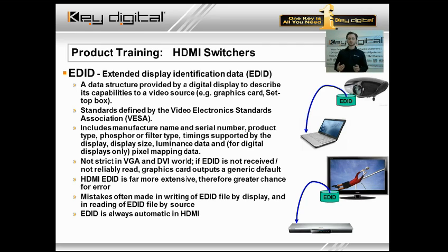Whereas in the past, the installer certainly had more control in the analog world over what resolution the source device was outputting at all times. In the HDMI world, essentially it has become automated, where the display again sends that EDID file to the source. The source complies, outputting 1080i, knowing that the display itself is not capable of 1080p. That's assuming that a nice solid read is established.